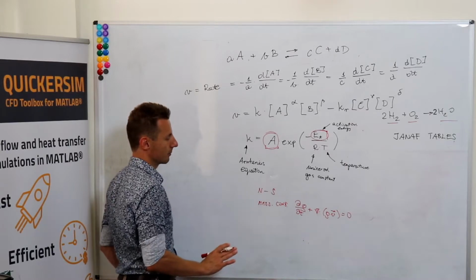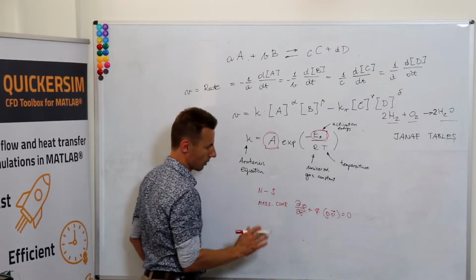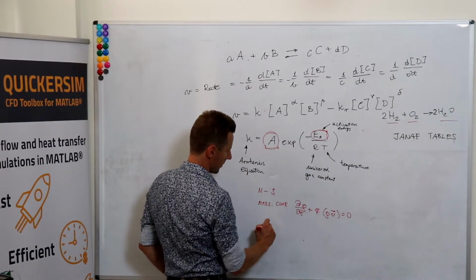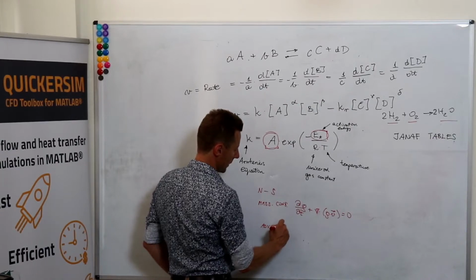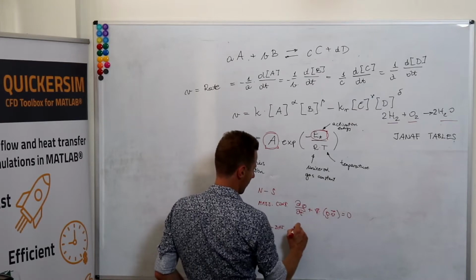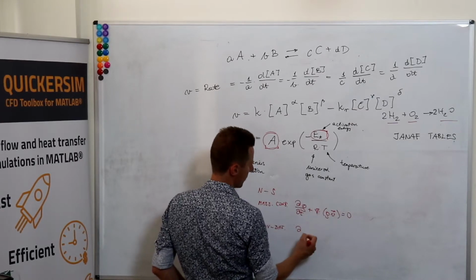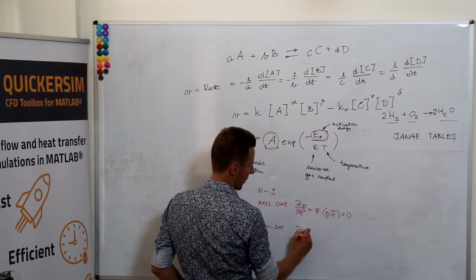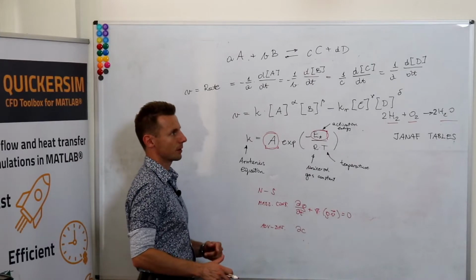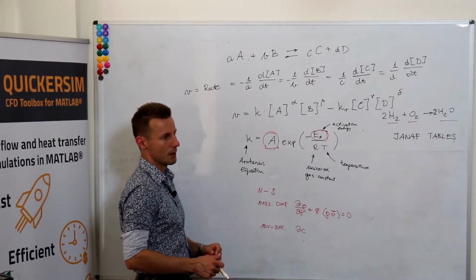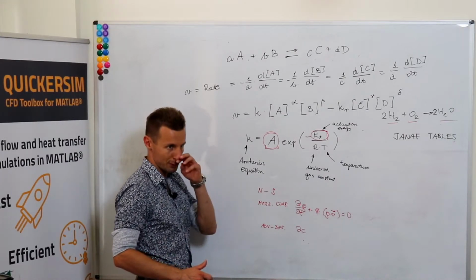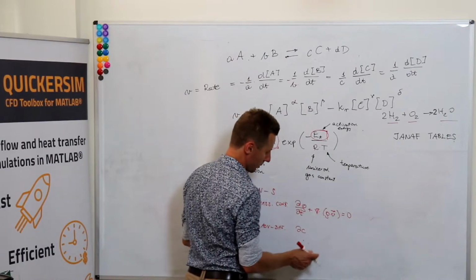So you're adding an advection diffusion equation for each species. So let's say we would have, well, you need to play around with the coefficients. Let's say we've got some concentration. Concentration could be, you can define it in moles per cubic meter. You can define it as kilograms per cubic meter. It doesn't matter so much, but you need to be consistent.